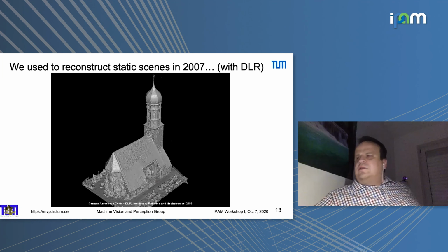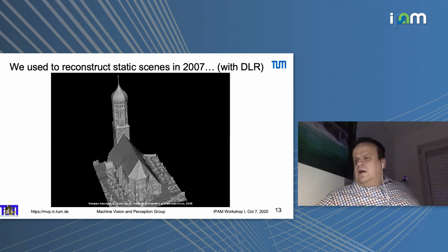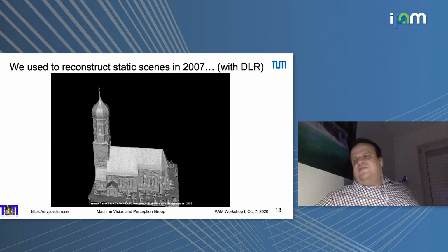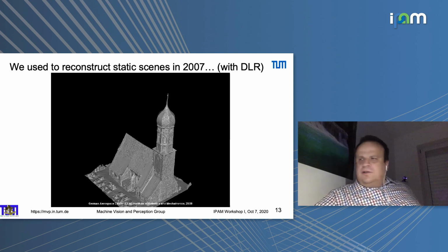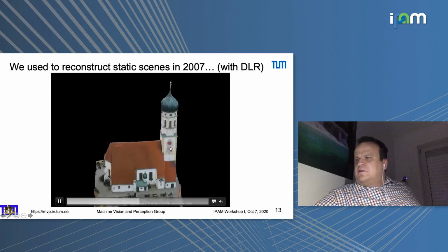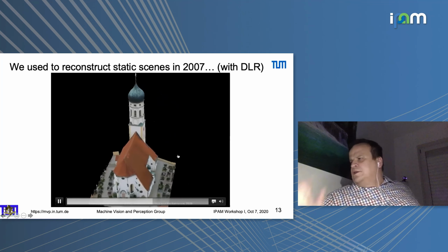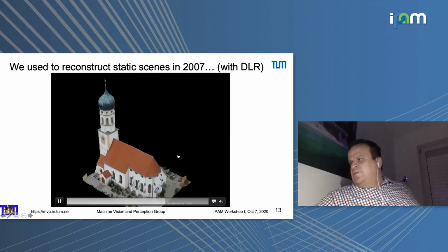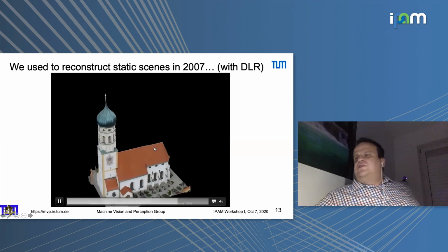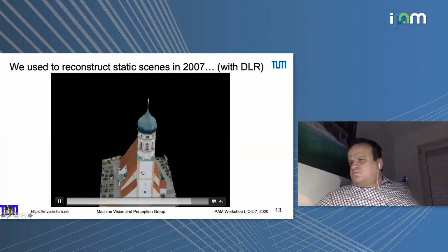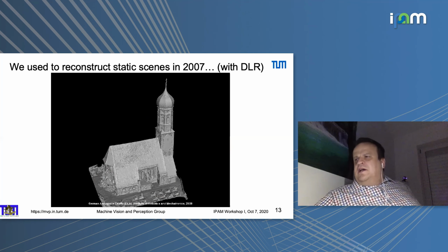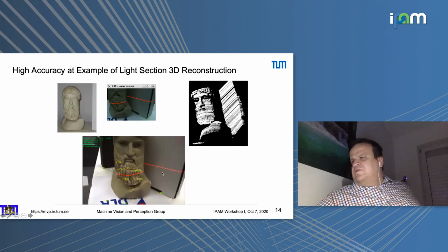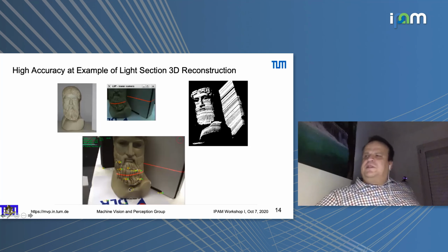So this is basically the direction of motion in which the camera was flying. And we used it to build from the 60 images this 3D model with an accuracy of 1.5 centimeters. You can see in this model even the solar clock on the tower, somewhere here. I noticed the solar clock only after looking at the 3D reconstruction. There was a small notch sticking out of the wall. So this is something you can do with a monocular camera, just by stitching information from images. To show the accuracy, we used it of course also to stitch information between different image frames.